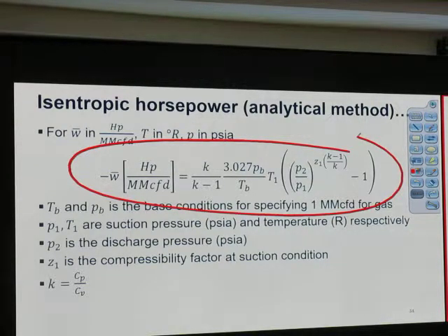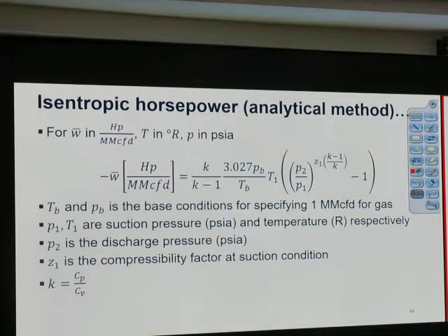Okay? So the suction temperature of stage 2 cannot be lower than the ambient temperature. Agree? Chris? Why is that? Because it's inside the... Can it be lower than the ambient temperature? What's your comment? You're cooling it with an ambient temperature intercooler, so you're not going to get it lower than that. Yeah, correct. We use the ambient temperature to cool it down, right? So it cannot be lower than that. Good? Alright, the rest is just put the number in and do the calculation, add them together.